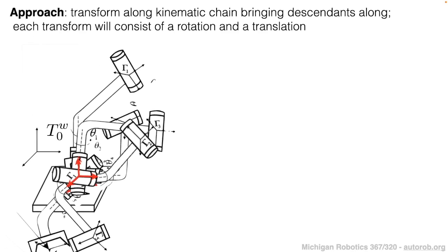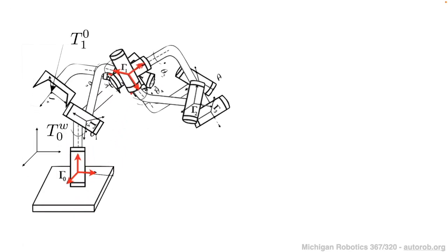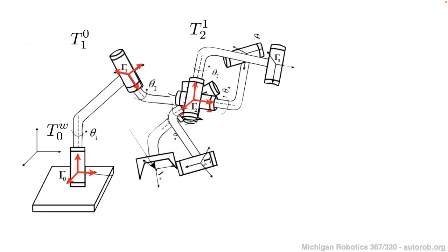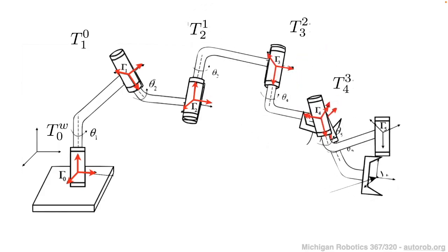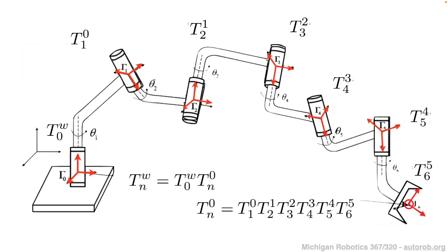So you can see we're going to translate all of the links together by this translation, and then we're going to move to link 1, and we're going to transform it according to the joint that it's attached to as its parent joint, where we're going to transform the rest based on link 2 and link 3 and so forth until we've walked through all of the links within this kinematic chain, and we'll end up with the position of the end effector.